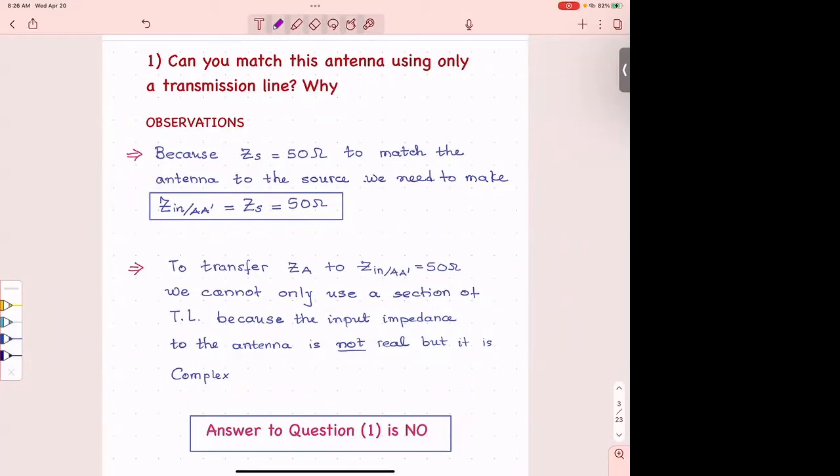So whenever I give you a problem in the final and tell you, you have this kind of antenna, this load, I give you a real number. And then I give you the internal impedance of the source. It does not have to be 50, it could be 100, it could be 80, whatever the source is designing. Then you can always find a transmission line of a quarter wavelength or higher quarter wavelengths to be able to match it. But when you go to higher quarter wavelengths, only add multipliers, not even.